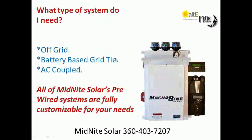So if you're starting from scratch, you don't have any renewable energy, and the utility grid is already there, and you want to do grid tie, then you have two choices. Do you want to do battery backed up grid tie, or do you want to be pure grid tie with no batteries? We won't even go into pure grid tie here, just because you don't need a pre-wired system for that. But with pure grid tie, when the grid goes down, you do lose your power.